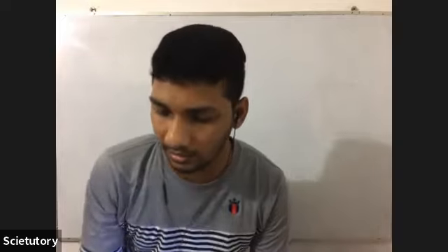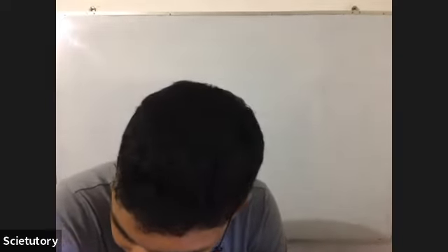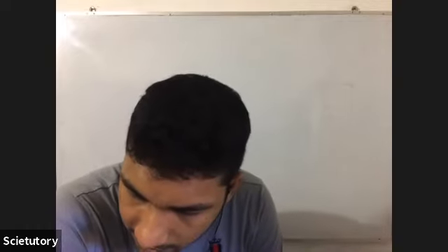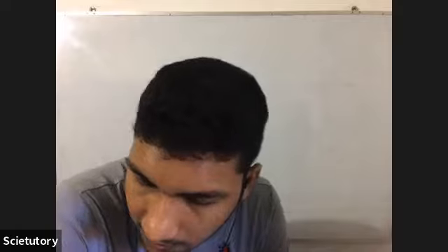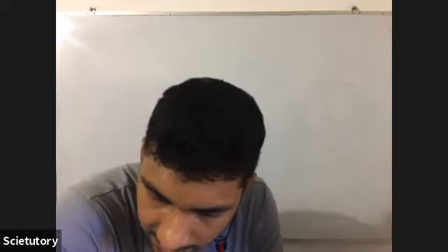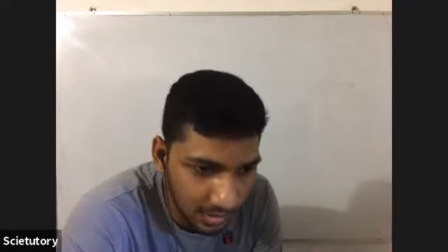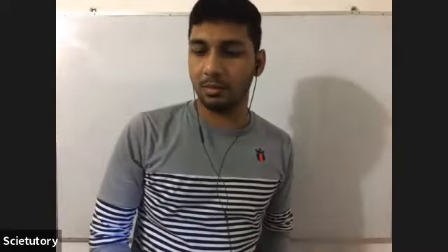Okay, so this is the maximum volume that can be replaced while keeping the vessel floating, V. If you replace a little bit more than V, it's going to go inside, it's going to immerse. The initial volume of oil is V naught. Then the ratio V over V naught is given by assuming that at the end of the process there is a certain amount of oil left in the vessel. So you are keeping the oil to some extent. There is an adequate amount of oil initially, so something remains at the end also.